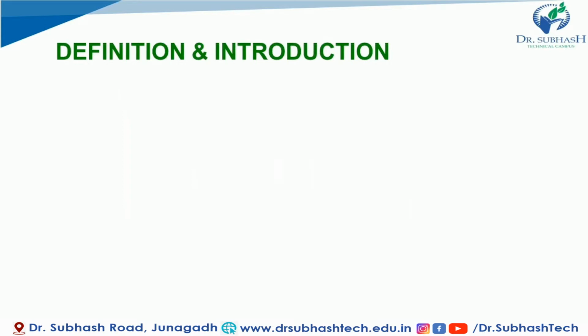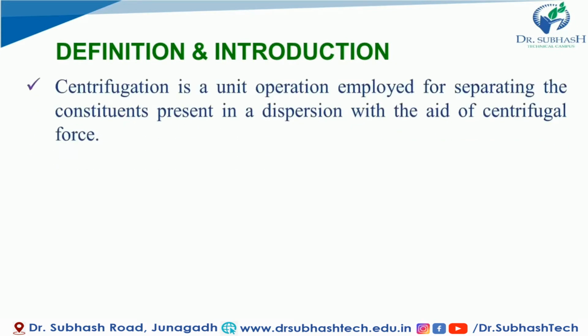Today we are going to focus on centrifugation, as I mentioned in my last video lecture. First of all, we are going to see the basic things about what centrifugation is. So here is the definition. Centrifugation is a unit operation employed for separating the constituent present in a dispersion with the aid of centrifugal force.